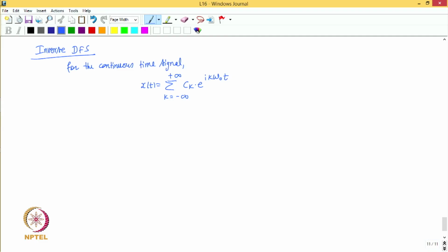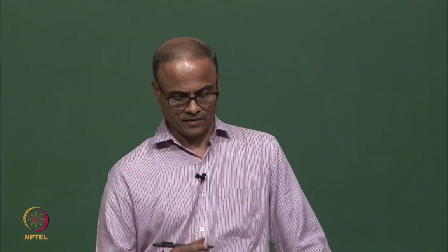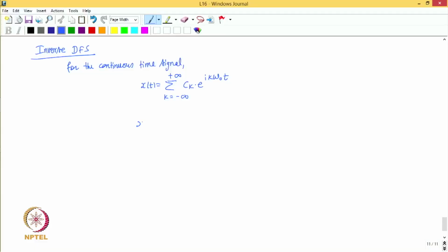And now here we are going to incorporate modifications in various variables, taking into account the discrete nature of the signal. Therefore, x of t we can simply represent as the discrete signal xn, and then we have the summation. We have n distinct frequency components, and therefore we will use only those n distinct frequency components to reconstruct the signal, and hence we are going to use the components from k is equal to 0 to n minus 1, right.